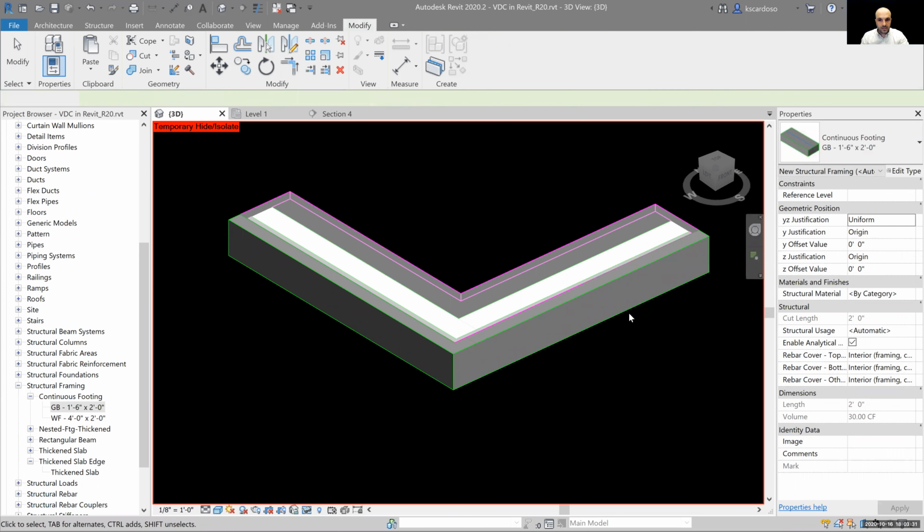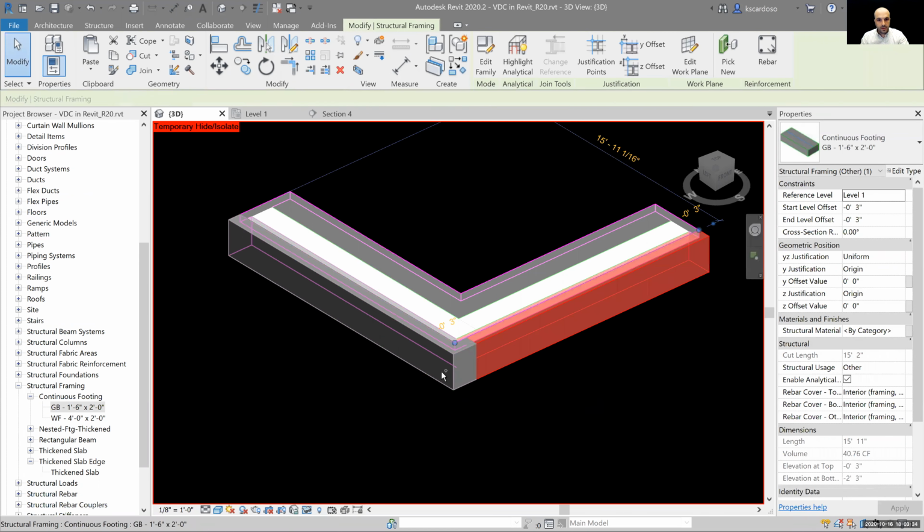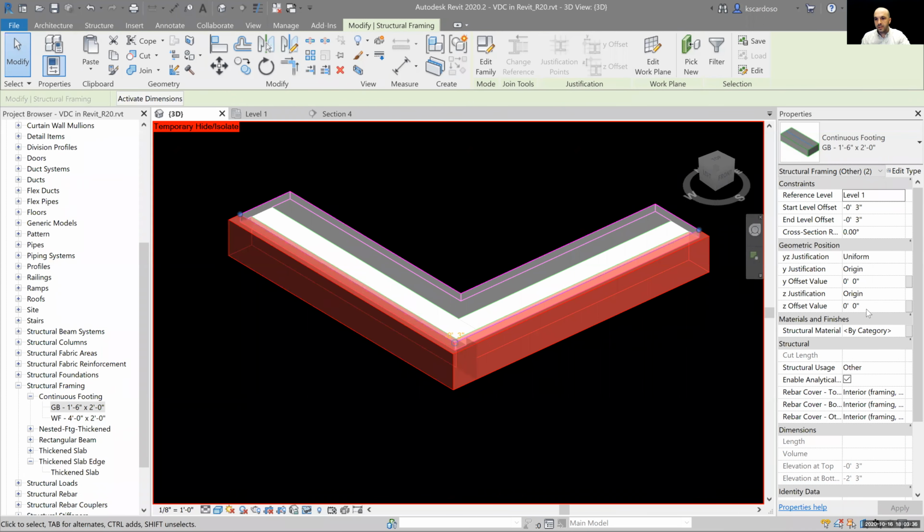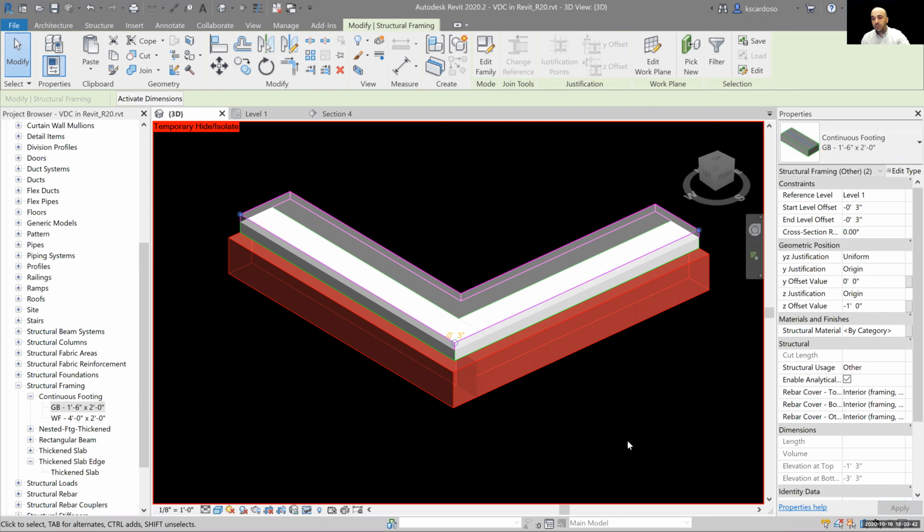And then I select my beams and I play with this offset here, -1 foot. Is that wrong? No, it's not. But look at how many steps we took, right? And you increased the room for error. Not only did you use 3D snapping to offset a beam to its original location of -3 at the start and the end, but now you added more complexity and said, yeah, but it's really a foot below that. Okay, you could still argue, but there's nothing wrong with that. My mind thinks that way.